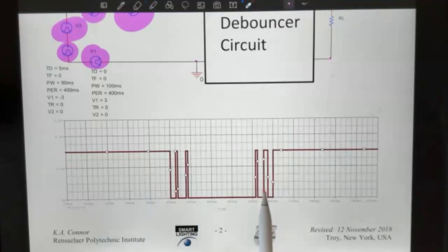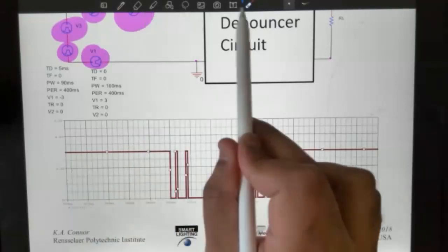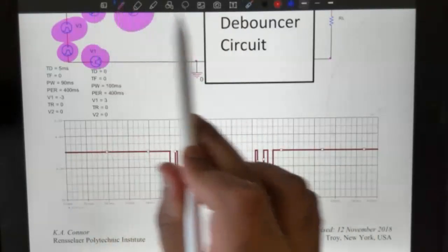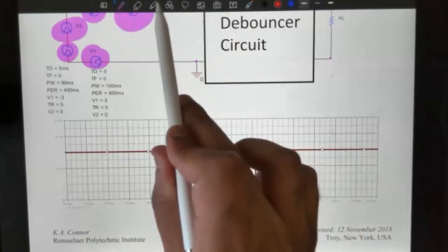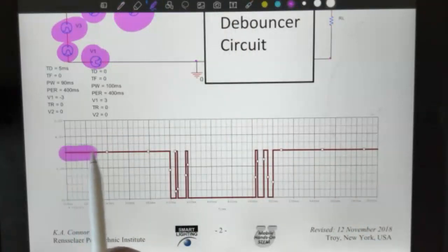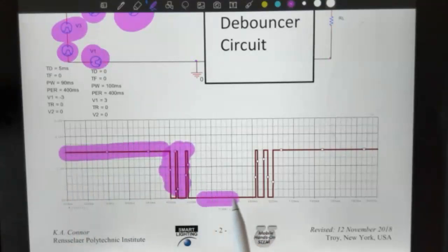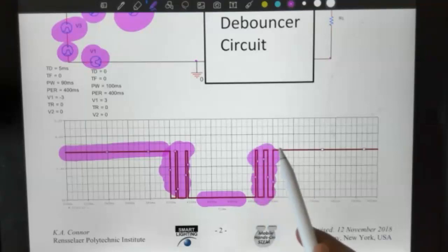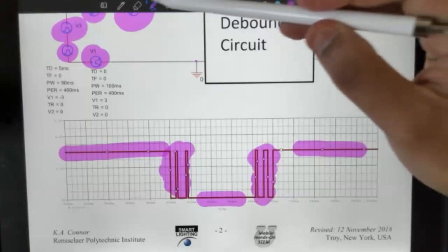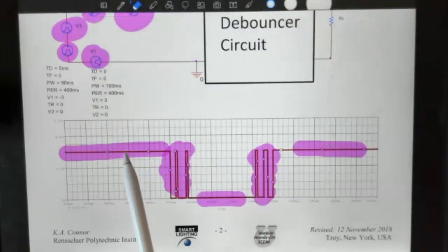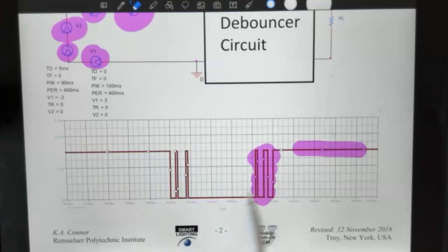We have staggered the low and high states and the periods so that you get the combined effect of a voltage source that has a high state, then bounces for a little bit, then goes to low, then bounces again, then comes back high. So we have used several voltages with different values to build a model of a bouncy switch in PSpice.